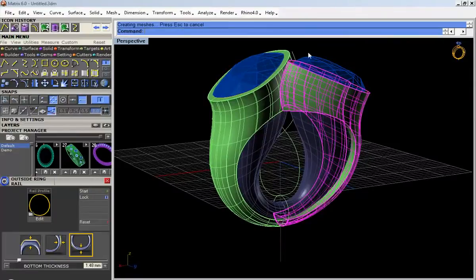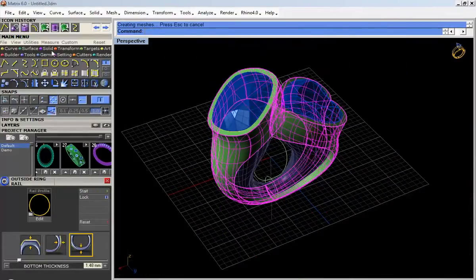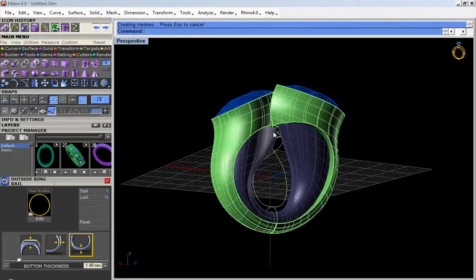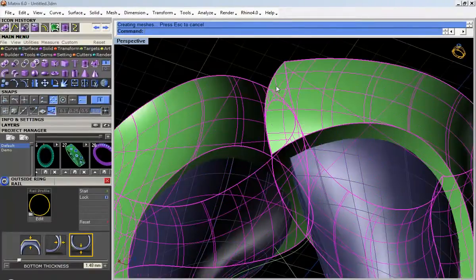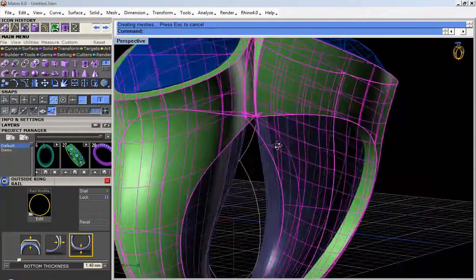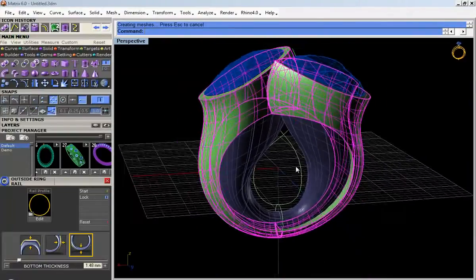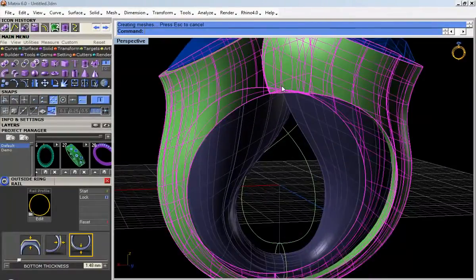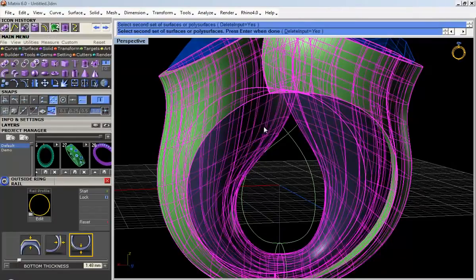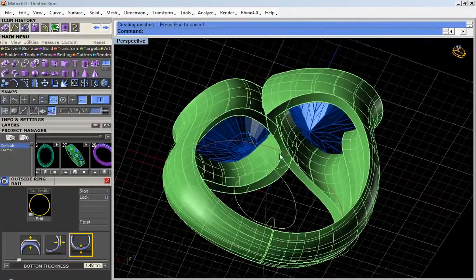They're not one now, so I'm going to select them together, then do a boolean union, which is over here, and it's successful now. You see, they are united into each other, no longer different. So that's how you do the boolean union. And now I'm going to try to do a difference, and there you go.